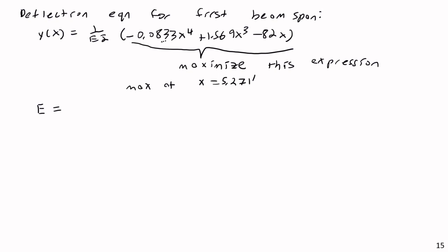While it might be tempting to use inches and inches to the fourth power for this and KSI for this, the one problem was that on this particular one I can't just go back and convert the length to inches. I did this whole equation in foot-kips, basically units of feet, and to tease back out the multipliers I would need to get it back into inches, unless I carried the units all the way through, is probably just not worth it. The path of least resistance, once I already have equations with coefficients with units that have disappeared, everything baked into the constants, is just to convert my E and I to feet rather than trying to convert these back to inches.